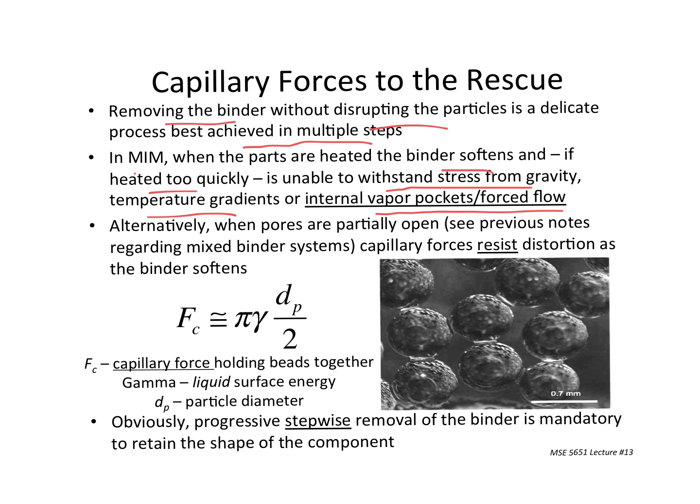So if we'd had the ability to apply a lot of pressure to those zinc oxide components, which we don't, then we could have counteracted all that pressure, and it would have been forced to come out through the available spaces, even though that would have been pretty slow. But anyway, that last part is what we're talking about in terms of the previous slide. But we still have to deal with the fact that these are heavy metal particles, all right? Gravity acts on them very efficiently if they're 9 grams per cc, okay? And so temperature gradients that can show up in these systems, especially when there's a lot of poorly thermally conductive binder holding everything together, all of these things have to be taken care of.